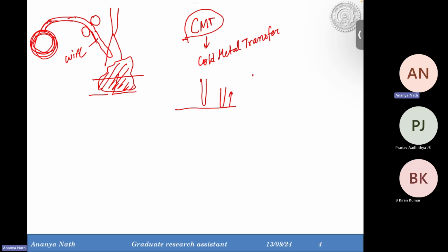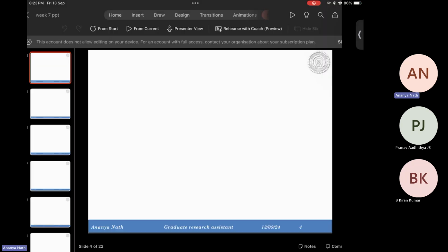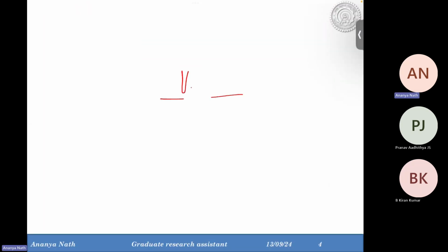When it retracts, there is a sudden jump in current, and that sudden jump produces so much energy that it makes one drop of melt pool out of that electrode. As you have retracted it from the build plate, there is now no arc or current passing through the electrode or build plate. You have just deposited one drop.